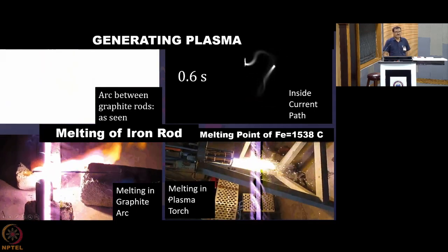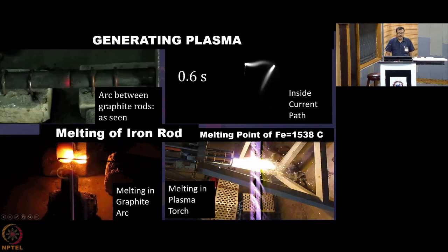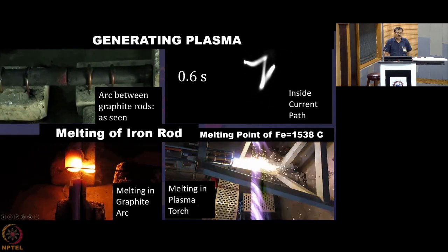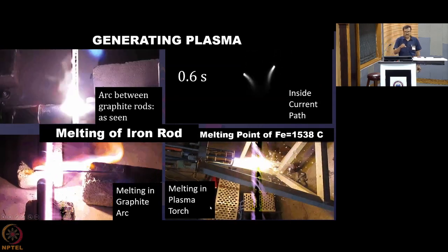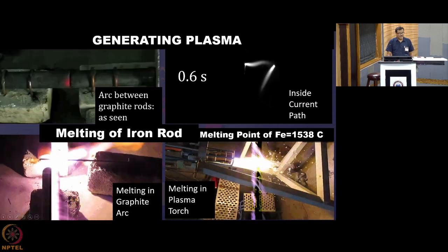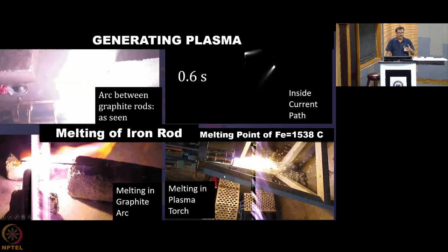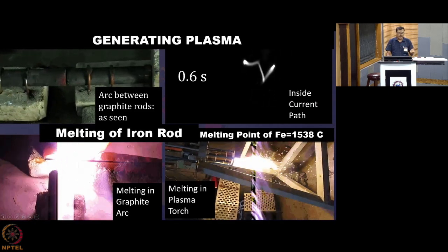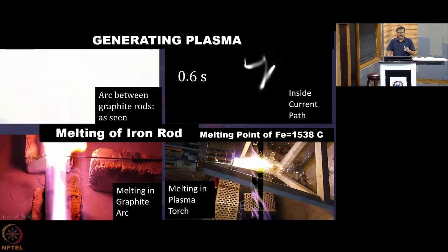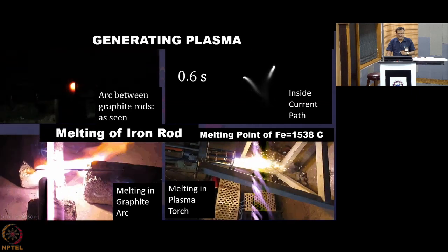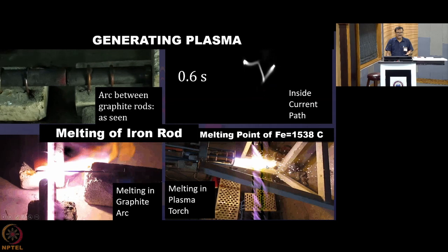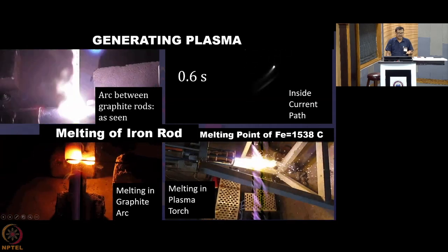And that is the technology of thermal plasma devices. What we have done, we have now tamed that random arc within this plasma device. What you are seeing on the lower right corner here is called a plasma torch. A plasma torch is a device where you are able to control the arc in a way that it persistently and continuously heats the gas that is passing through this zone, in a manner that it is able to reach a temperature of more than 1000 degrees centigrade very easily.